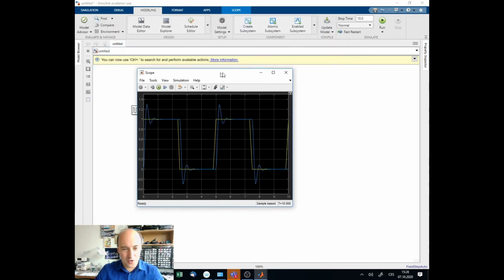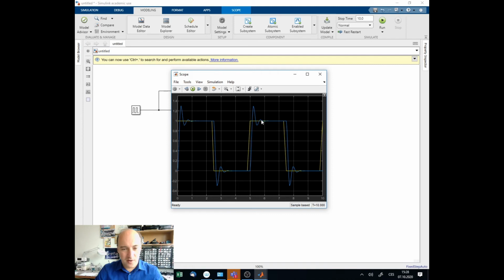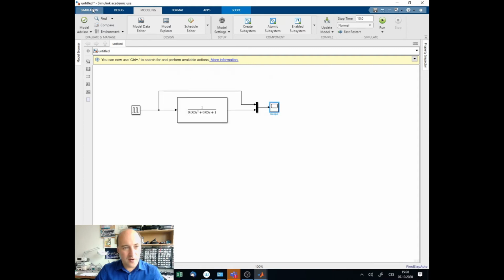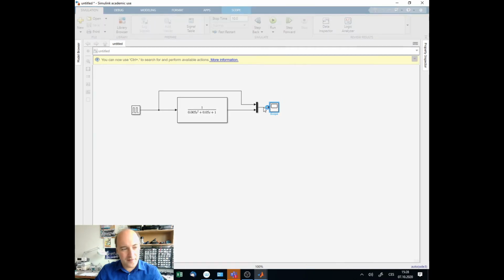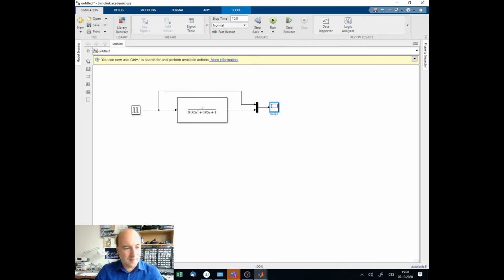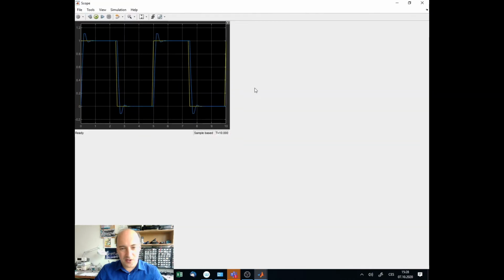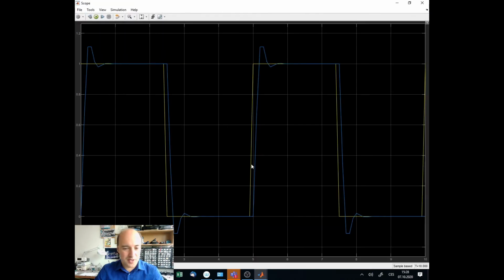So this was my variable step setting, and we don't have a fixed step size. Now if I run the simulation again, I now have a fixed step setting, and now you see that it was probably not a good idea to have just 0.1, because I see that now I have a problem. It calculates the response at this point and at this point.